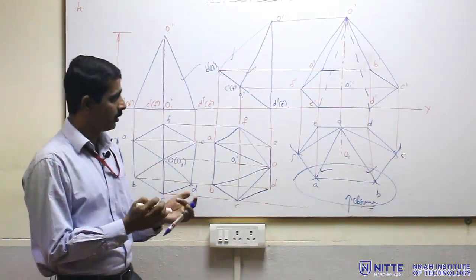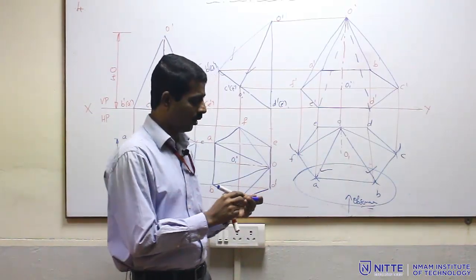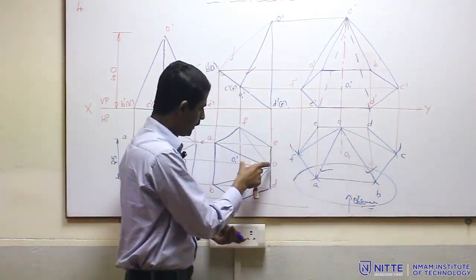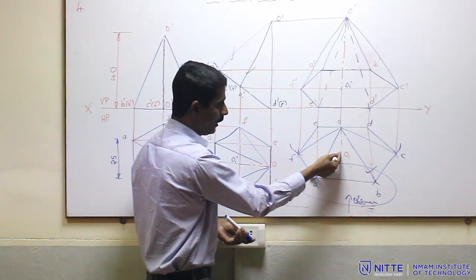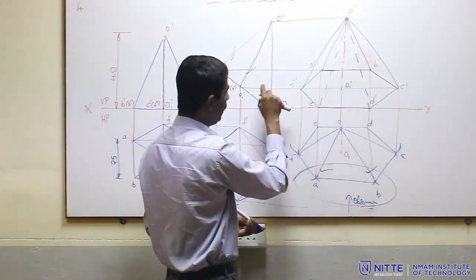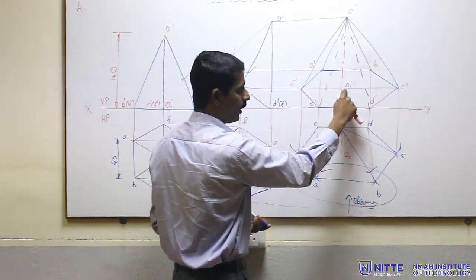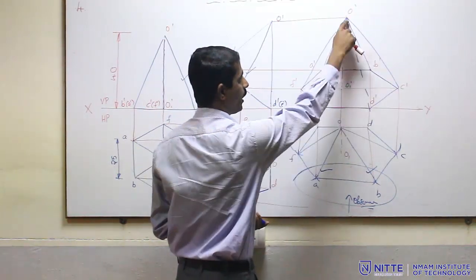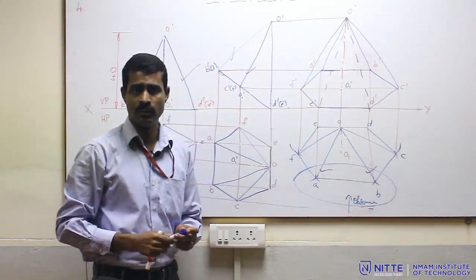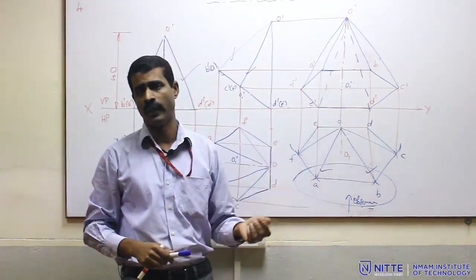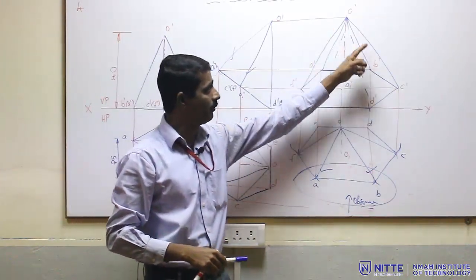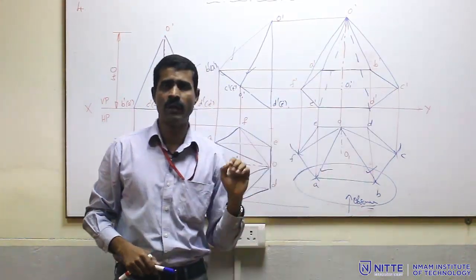So, I can complete the projections by drawing an axis here which is having this length, and O1 you project already is on the vertical line, O1 dash is here, you will get O1 dash. O1 dash to O dash is the clear axis which could have a thickness 0.25 mm. Okay, and all the visible and invisible edges are 0.4 mm thick.